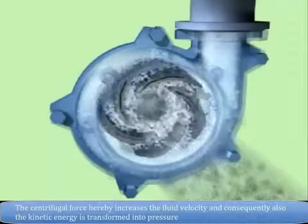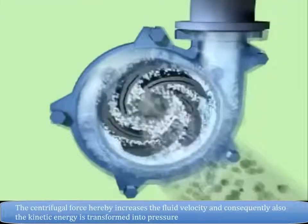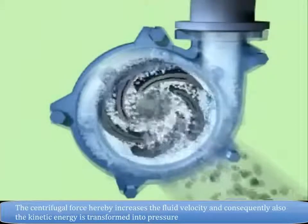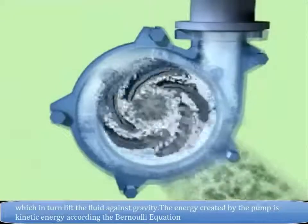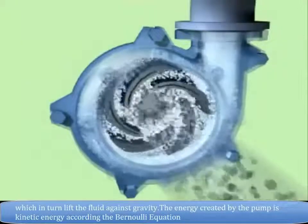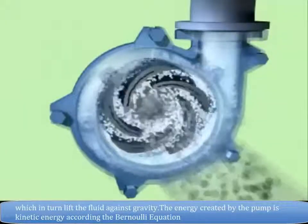The centrifugal force hereby increases the fluid velocity, and consequently the kinetic energy is transformed into pressure, which in turn lifts the fluid against gravity. The energy created by the pump is kinetic energy, according to Bernoulli's equation.